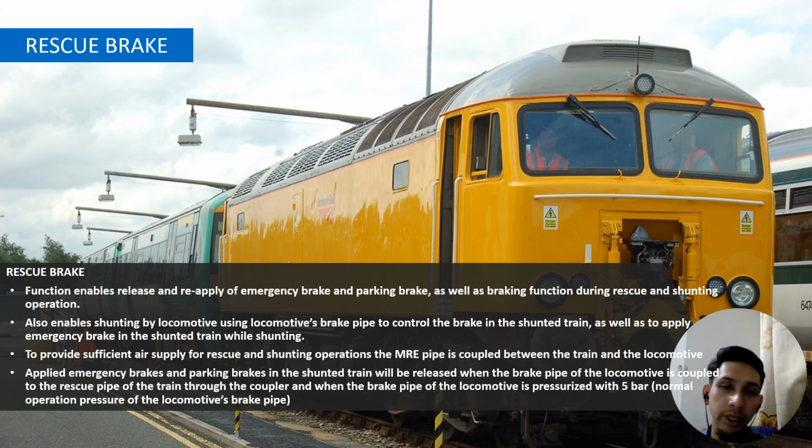The next brake mode is rescue brake. Rescue brake is a function that enables release and reapply of emergency brake and parking brake, as well as braking function during rescue and shunting operations. Also, it enables shunting by locomotive using the locomotive brake pipe to control the brake in the shunted train, as well as to apply emergency brake in the shunted train while shunting. And then, to provide sufficient air supply for rescue and shunting operation, the MRE pipe is coupled between the train and the locomotive.